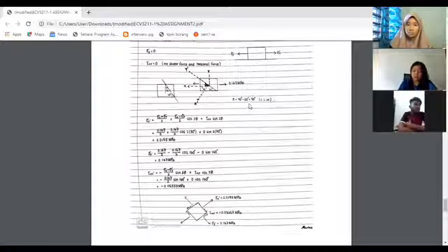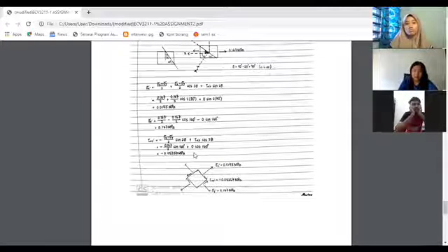So the angle is 90 degrees minus 20 equals 70. The sign is positive, since the rotation from horizontal x to the transformed x prime axis is counterclockwise. Then we just substitute the values using the formula below to find sigma x prime, sigma y prime, and tau x'y'.